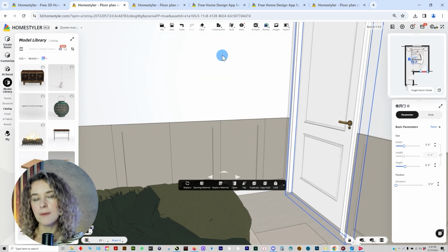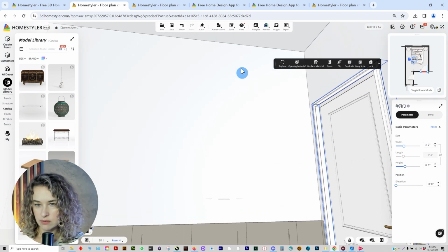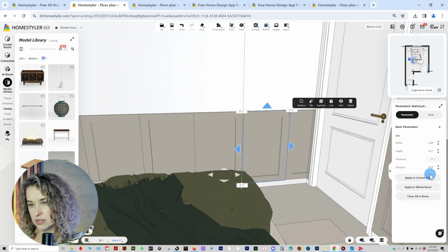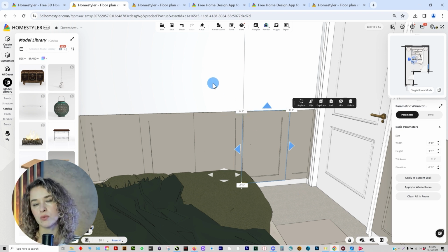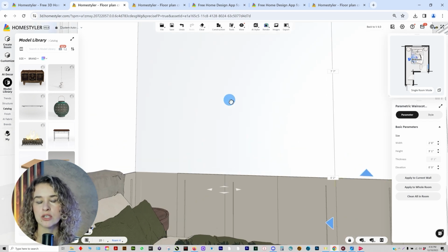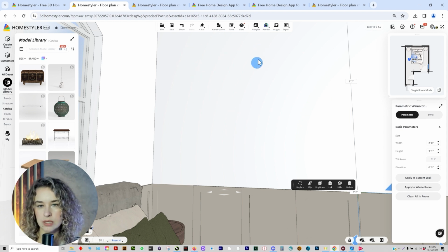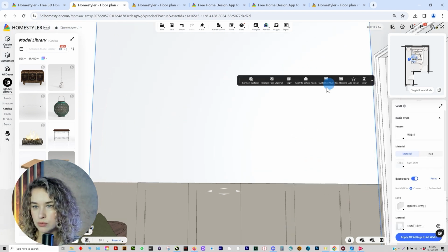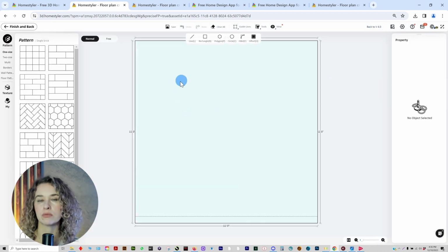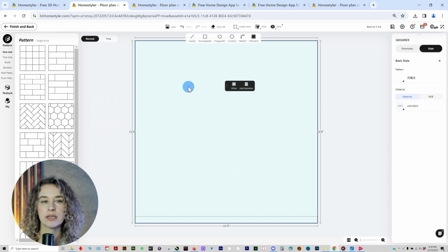So we have our wall height of 11 feet minus 3 feet for the wainscoting, and the baseboard is 5 inches. With some extra, it's around 8 feet minus 5 inches, but we will keep this 5 inches for extra adjustment if we need to make those. So now what we do, this is the button, we click the wall, tile flooring button. It's called tile flooring, but it will lead you to the wall, and here you can apply your textures.